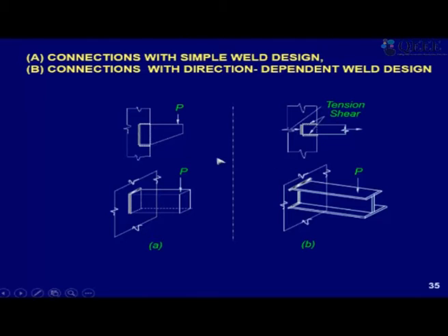Similar to bolted connections, we can also have what are called eccentric connections. Like if you imagine I weld along these three sides only, and I apply a load in the bracket, I have a CG of the weld group which will come somewhere here. So this is like a channel projecting out of the plane of the screen, which is under P into E, that is the torque. Okay, so torsional stresses will develop, which are basically nothing but shear stresses, and the stresses will be in proportion to the distance of the point from the CG of the weld group, weld line or weld group as we call it. Okay, so we first need to work out the CG of this.